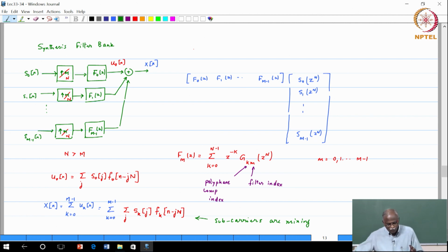Okay. So, any questions on what we have done as far as the redundancy? We kind of sowed the seeds for the notion of redundancy. Redundancy means that you have to use some additional resources. The additional resources that we are going to use is in the form of additional bandwidth. Additional bandwidth means your sampling rate has changed. So, that means your sampling rate is a bit higher. So, therefore, upsampling by n and not by m.